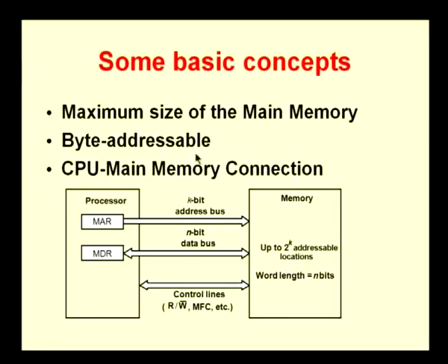Most of the processors today, when we talk about memory, we normally refer to it in terms of byte addresses. The actual length of a word could be even greater than a byte. Let us say for instance a word had 32 bits, that is, it will actually have 4 bytes in it. So, the memory may be organized as words which have actually 32 bits or 4 bytes. But when you have 4 bytes in it, and if you say that the memory system is byte addressable, then it would correspond to 4 different bytes.